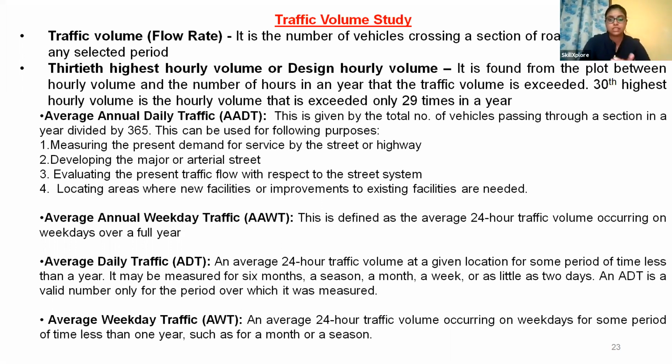It is measured by the present demand for service by the street or highway, for example a major or arterial street. Then average annual weekday traffic. Here the 24-hour traffic volume is stressed. Then average daily traffic. Here the traffic at a given location for some period but less than a year is considered. Then average weekday traffic, here on weekdays alone for some period of the year less than a year, such as for months or a season. So everything is different.